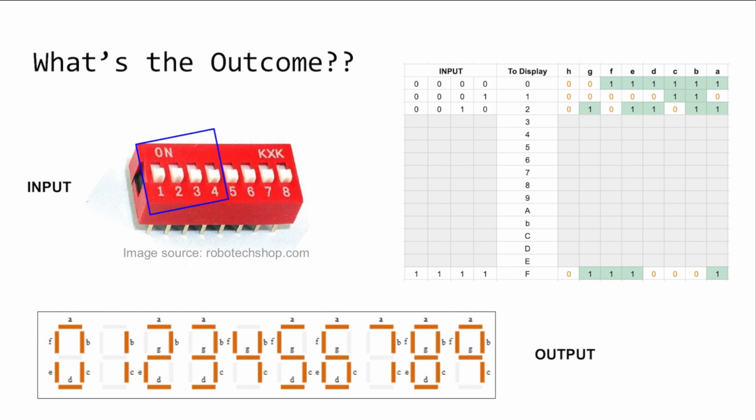Okay. So what's the outcome of this lab? So we would have this 8-bit input. So it's like an individual switch at every number. So we will only be using 4 pins over here because 4-digit binary numbers are enough to represent hex 15 numbers, right? So from 0 to F.